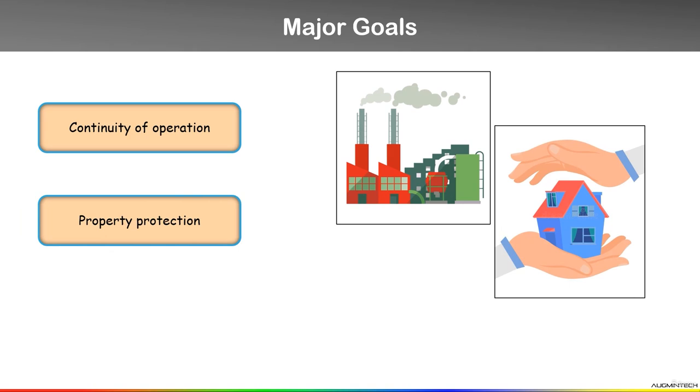Can you tell me how to prevent property damage in case of fire? For that, we have to design the structure to slow the spread of fire. For example, we have to place self-closing fire doors and we have to install fire dampers in the ductwork. When you install a fire damper in the ductwork, it can slow the spread of fire. Then we have to follow important safety protocols also. For that we have to clean up dust and debris. Then we have to store flammable materials properly, as per OSHA or any standards.